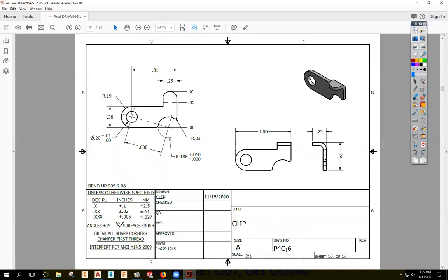See, also here, what's this kind of dimensioning called? Ordinate. So I have ordinate dimensions here because the edge of the part, a bend line, the other edge of the part. I said I like to use them for bends. Okay. And what kind of dimensioning is this? Baseline. So I measure from the right side over, right side over. Okay.